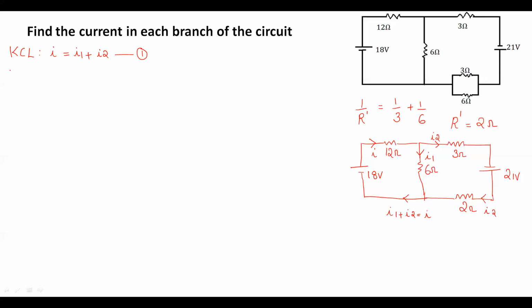So as the next step, we would apply the Kirchoff's voltage law for any chosen loop. So let me mark these points in order to identify the loops. All right, A, B, C, D, E, F. Now choosing this loop, A, B, E, F, A. So this is my preferred direction. I prefer going clockwise in this loop. Not necessarily. According to your convenience, you can choose clockwise or anti-clockwise, but because most of the currents are moving in this direction, I prefer clockwise direction. That's all. So let's begin applying the loop rule.